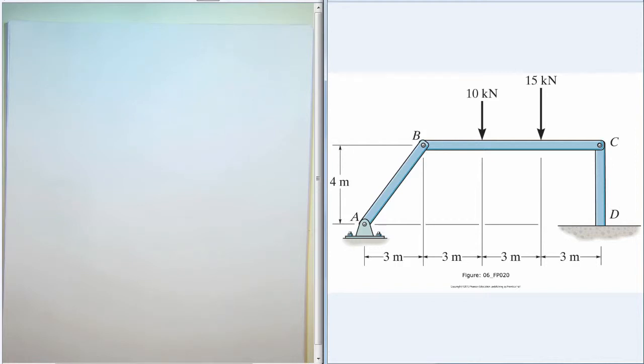It's AB. AB is a rigid body with 2 pin joints and no loads at any other points, no forces at any points other than those joints, A and B. So we know, so we don't have to draw the free body diagram for AB.